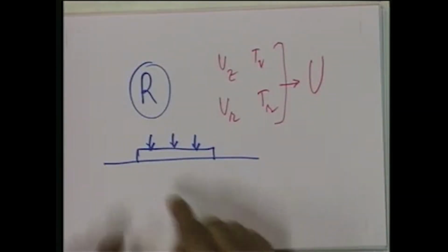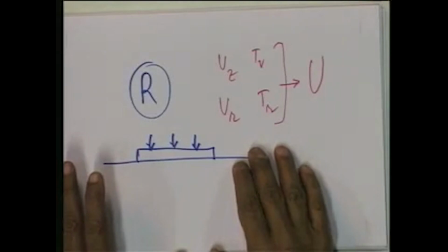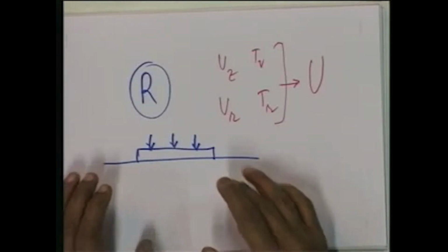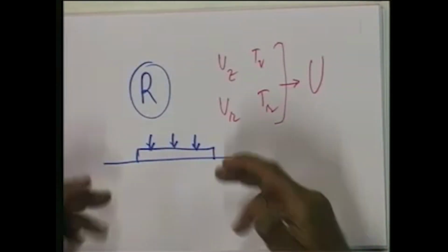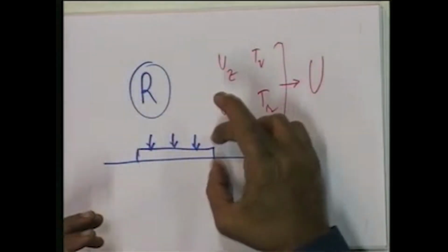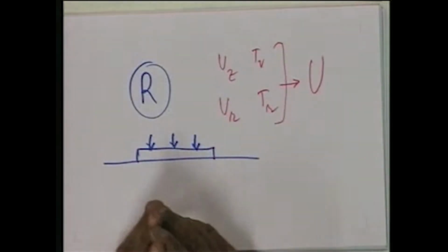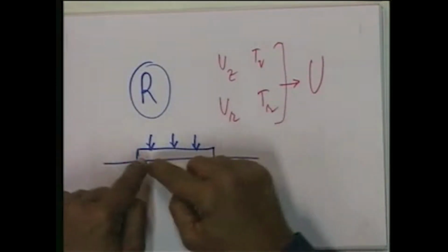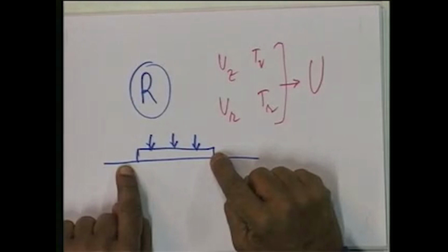That is, if this loaded area is flexible, then we know that the strain is going to take place freely. If on the other hand it is rigid, the strain induced in the soil will all be equal under the loaded area at all points.